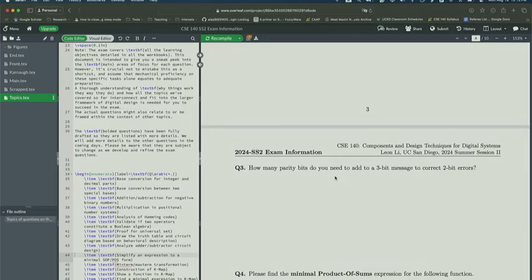And let's say 2-bit error, you still have to reserve one scenario for the no error communication. And sometimes when we talk about 2-bit error correction, it also includes 1-bit error. It's saying really up to 2 bits. Right? 2-bit error typically means up to 2 bits, unless we tell you exactly 2 bits. So you have to again include m and p.